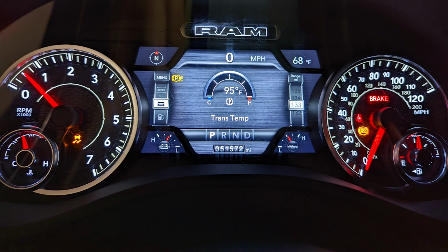If the transmission temperature is over 100 degrees, we would advise you to shut off the engine and let the transmission cool down to below 100 degrees before proceeding. The lower temperature will allow you enough time to perform the next fluid leveling steps. Remember, the transmission temperature should not exceed 122 degrees at any time while you are performing the final transmission fluid leveling check. Exceeding 122 degrees will result in an incorrect transmission fluid level.